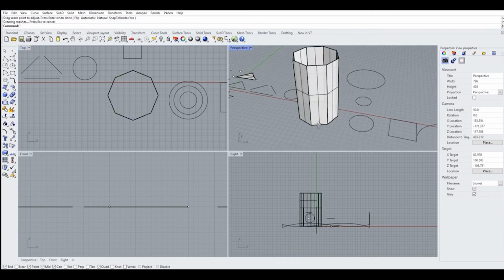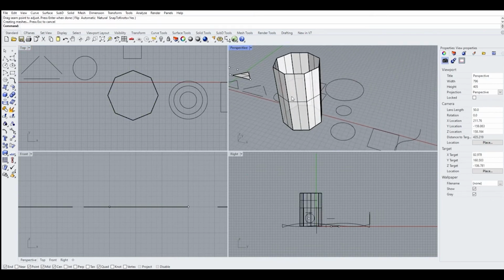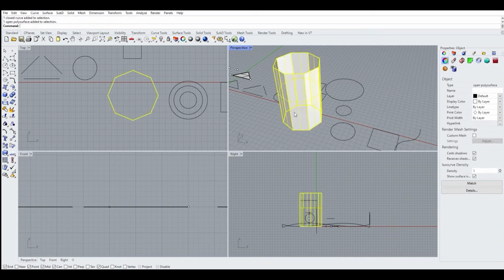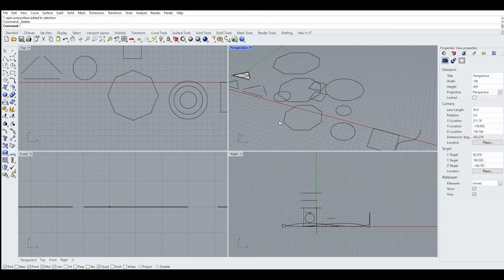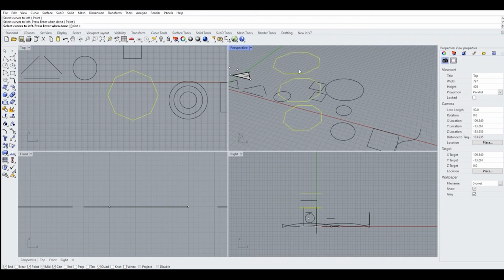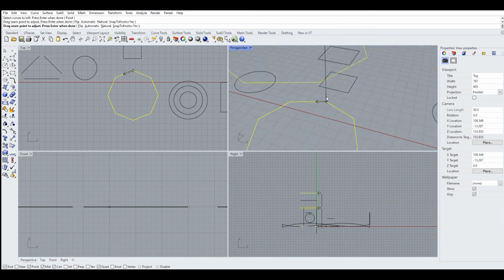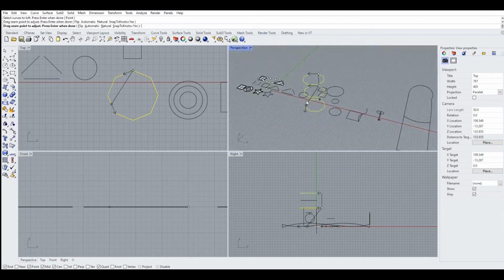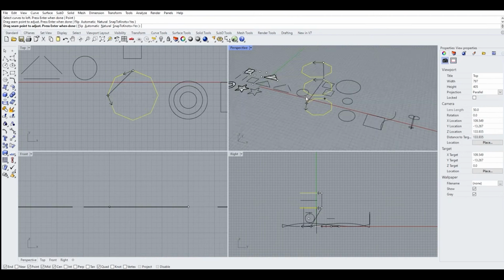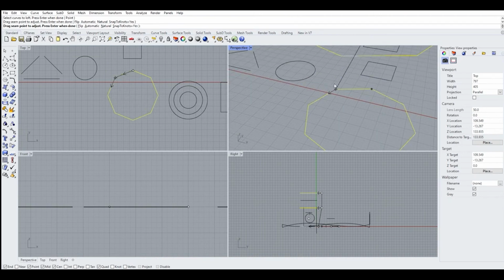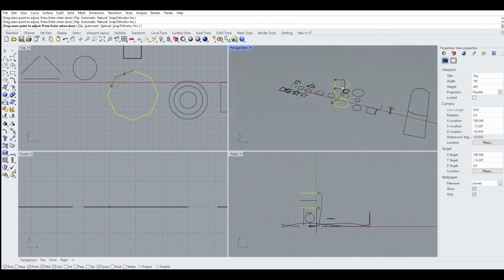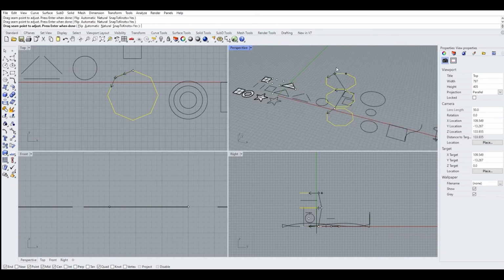And you'll see it connects all of those surfaces perfectly, but it uses the cross-section curves I selected to build the surface through. I'm going to do that again, but show you something different. So I'm going to right-click to reactivate the same tool, or you can go here and say Loft, select the bottom one, the middle one, and the top one. But I want to edit the flow of that surface. I do that by clicking on a point, single click and let go, and then I move the point to where I want. So I'm going to move it to that end there and click to anchor it there. And the next one, I'm going to click as well and move to the same point.